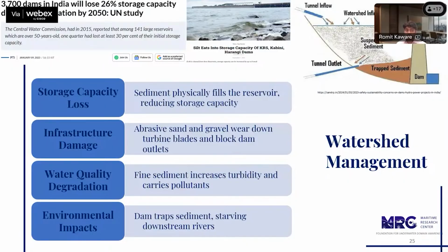Now this entrapment leads to loss of storage capacity, but it can also endanger the structural stability of the dam itself. In fact, if most of this entrapped sediment gets redistributed, it affects the water quality as well. If that sediment contains metal pollutants or heavy metals, how does that affect the water quality and the benthic health? This might also affect human health, so it has far reaching consequences, rather than just the turbidity. So we really need to look into that environmental impact.